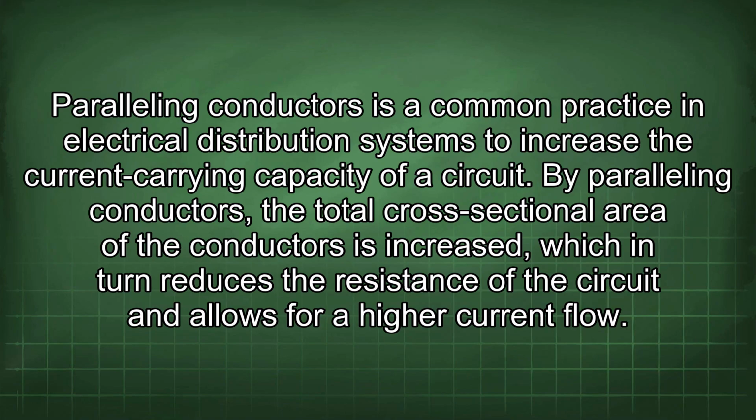Paralleling conductors is a common practice in electrical distribution systems to increase the current carrying capacity of a circuit. By paralleling conductors, the total cross-sectional area of the conductors is increased, which in turn reduces the resistance of the circuit and allows for a higher current flow.